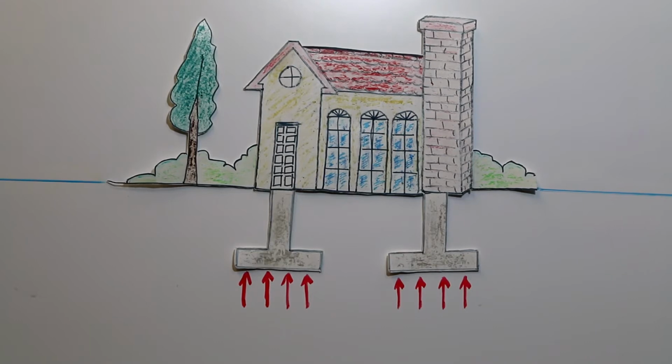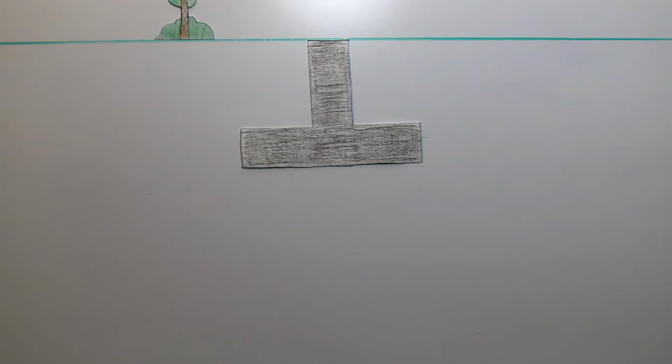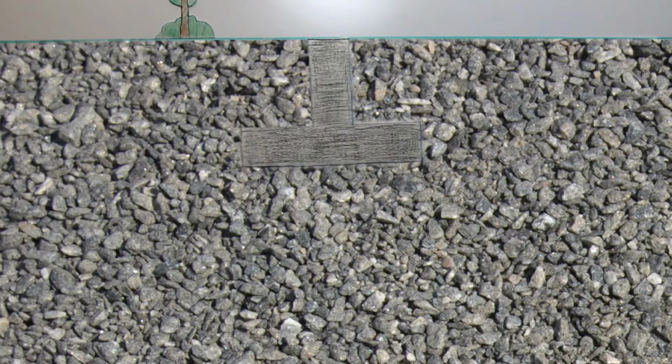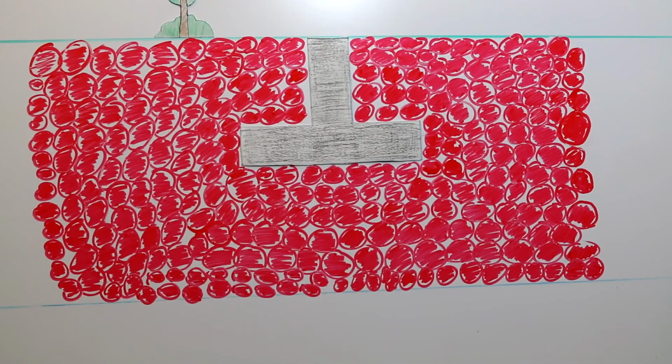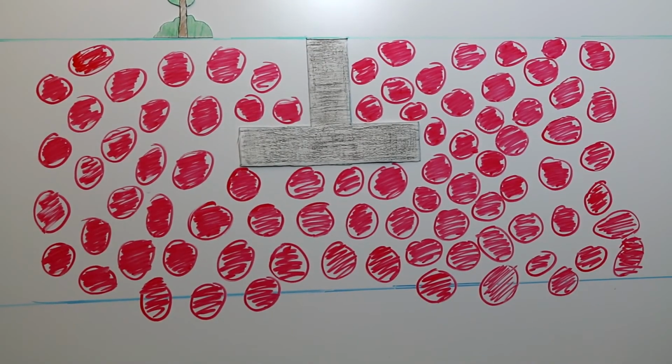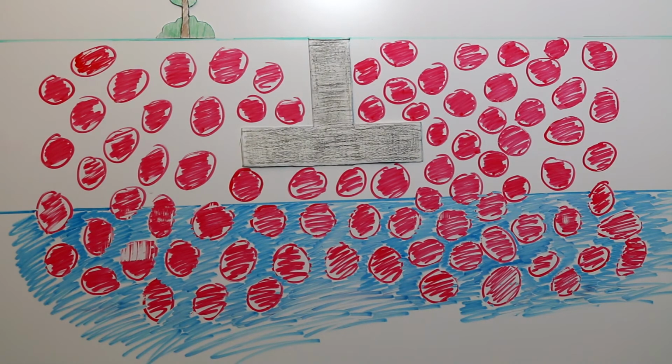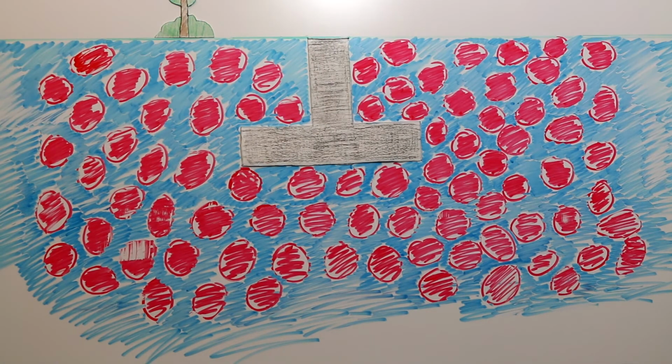The bearing capacity of soil depends on many factors. The main factors are soil type, which can be clay, silt, sand, gravel, or most likely a mix of these; density, which simply put is the spacing between soil particles; water table level, which is the depth of the water below the surface; and water content, which is the amount of water compared to the amount of soil.